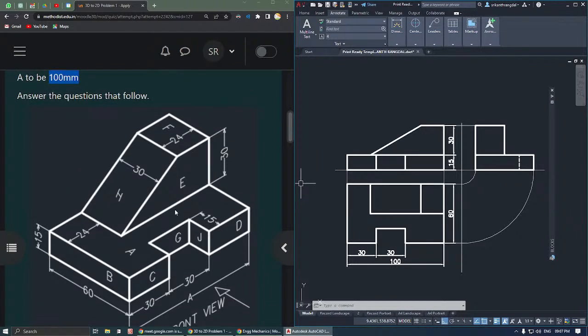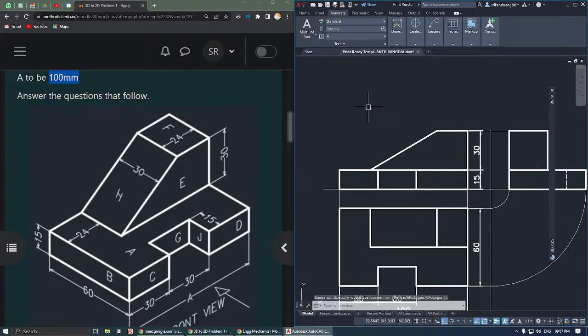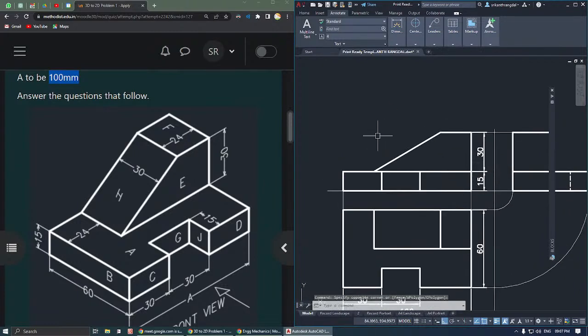The question was how to create the true shape. So I'm explaining the steps, watch it carefully. First I need to take O enter, T enter, and whichever face is inclined, we have to take an offset of that at some convenient distance.